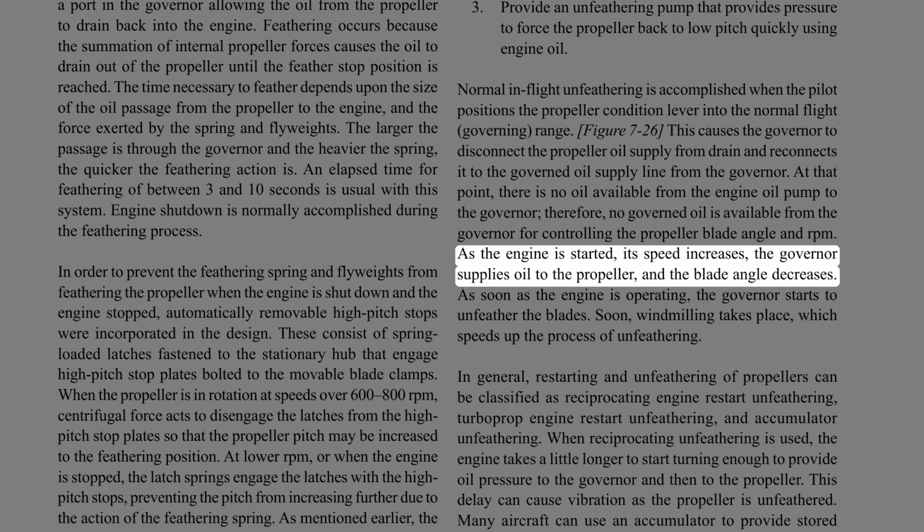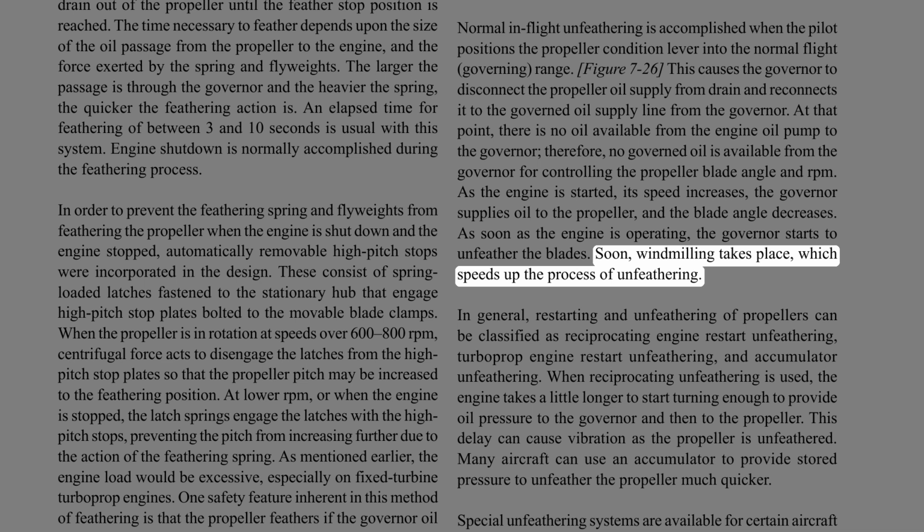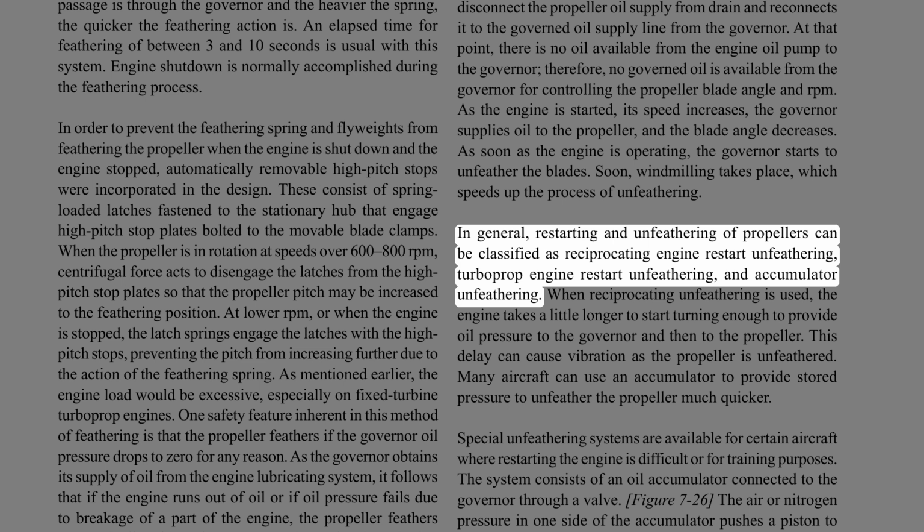As the engine is started, its speed increases, the governor supplies oil to the propeller, and the blade angle decreases. As soon as the engine is operating, the governor starts to unfeather the blades. Soon, windmilling takes place, which speeds up the process of unfeathering. In general, restarting and unfeathering of propellers can be classified as reciprocating engine restart unfeathering, turboprop engine restart unfeathering, and